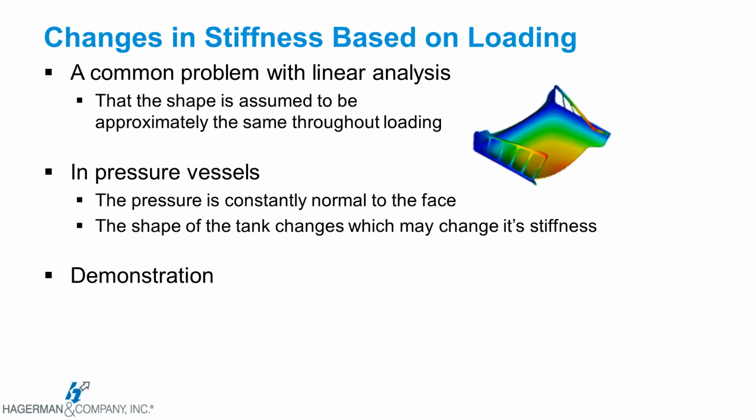As that paper tray gets pulled downward, the overall shape starts to deflect and gives us some strength back. Another really common example would be the bottom of a soda can. As the pressure inside the can increases, the dome will essentially stiffen and become stronger to a point, and we can simulate that effect within the Nastran environment.